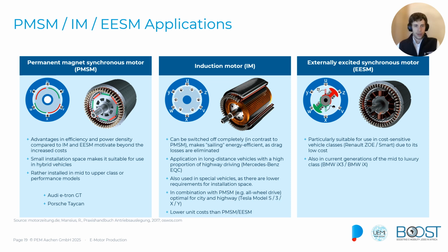And we find the induction motor, where the rotor is energized by the induction of the stator. This allows us to switch the motor completely off by simply not supplying the stator anymore. We often see this topology in combination with a synchronous machine in an all-wheel drive application on one axle, the front or the rear.